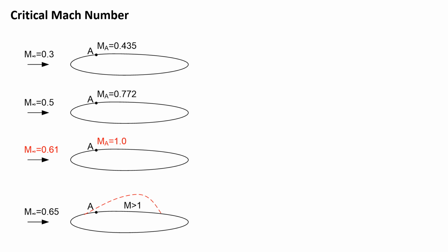Okay, and also through the discussion for the airfoil across the transonic Mach number regime, we know how to determine the critical Mach number. We just look into the detailed flow field over the airfoil surface, and if there is only one single point, or a very small region, that has sonic Mach number, then we determine that is the critical Mach number.